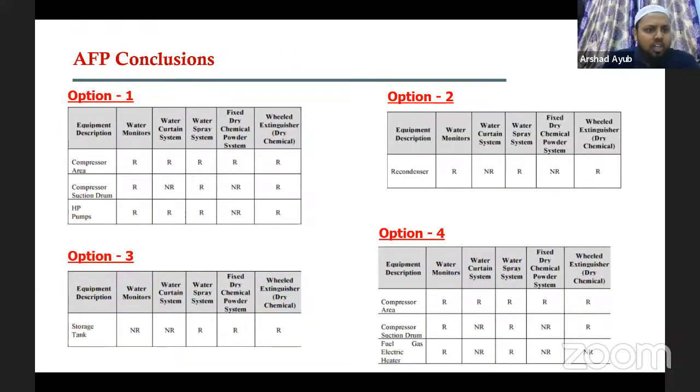Similarly, active fire protection systems. Each location or area might be covered with different types of active fire protection, such as water monitors, water curtain system, spray system, fixed dry chemical powder system, wheeled extinguisher system. You can even have fire hydrant, fire monitor, sprinkler system, everything. So you can give each active fire protection a rating, checking whether it is required or not. If it is required in that area, that option has a lower ranking. If it is not required, that option will have a better ranking.